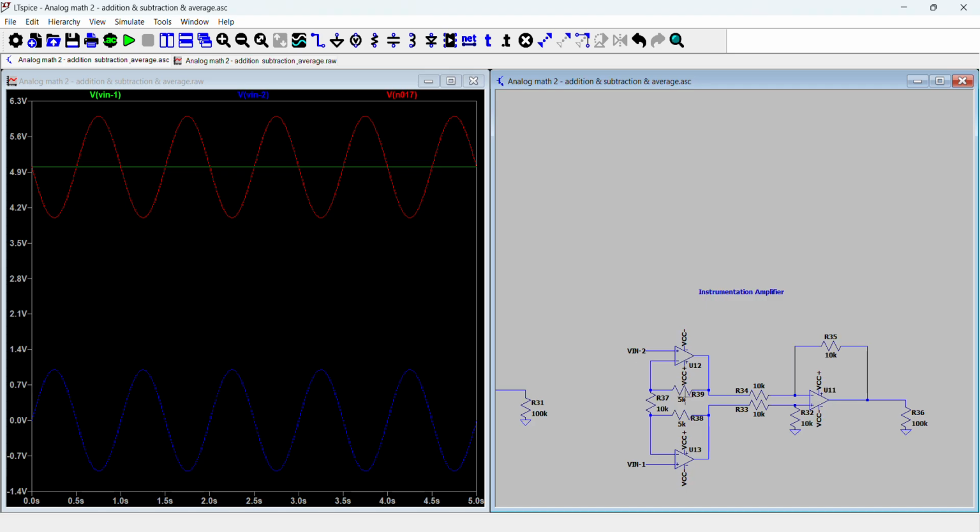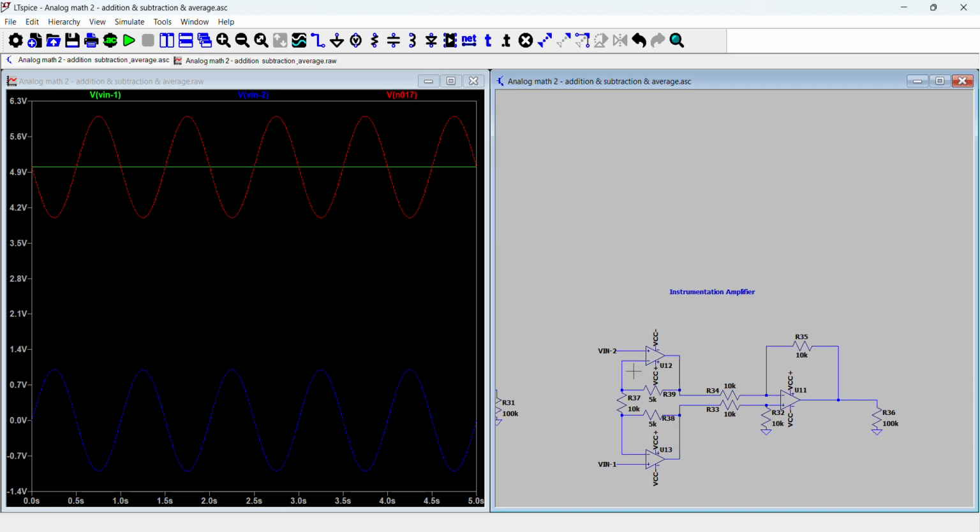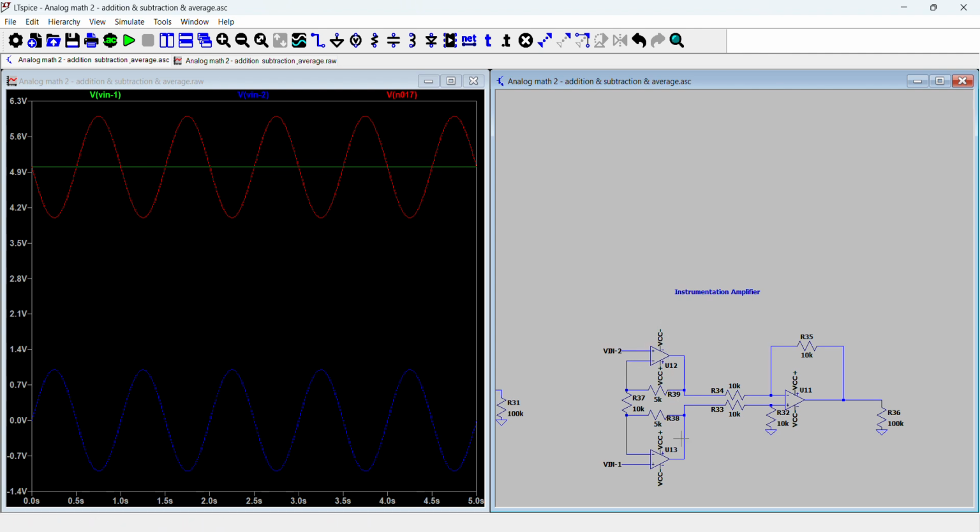And the way that we create a differential amplifier that way is we have to add this really large buffer stage, which will point the input at an infinite input impedance terminal. So in this case, the op-amp, because the input is now directly hitting the op-amp's input terminal, it's got an infinite input impedance. So it doesn't care if the input cannot drive a large current, because there's no current that's needed to drive the op-amp in this case.